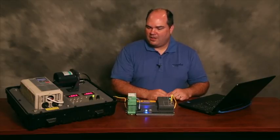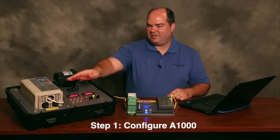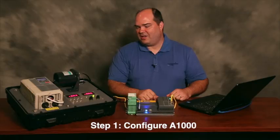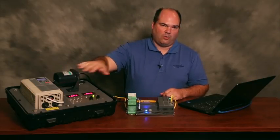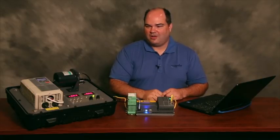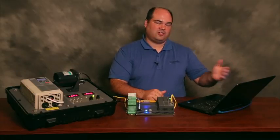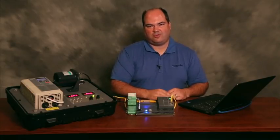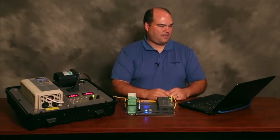I/O. In order to make these devices work together, the first thing to do is to install the Modbus TCP option card in the Yaskawa VFD and configure the VFD using either the keypad on the front or Yaskawa's Drive Wizard software. Once that's done, we're going to create a project in the Parker Automation Manager software, add the correct protocols, the code to write the variables and information over to the drive, and we'll test it out.